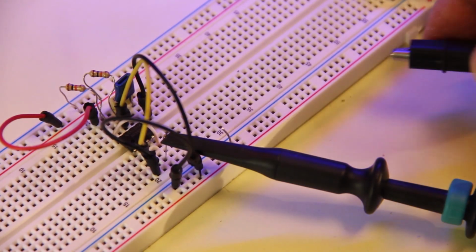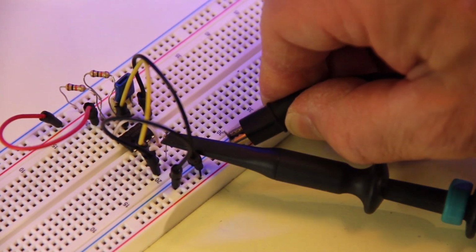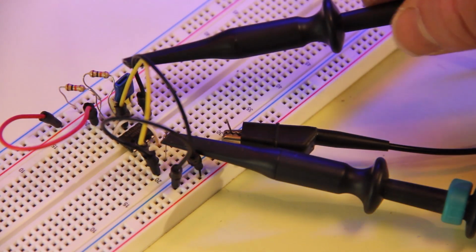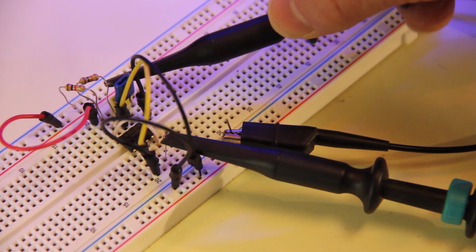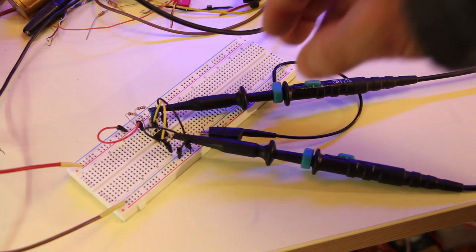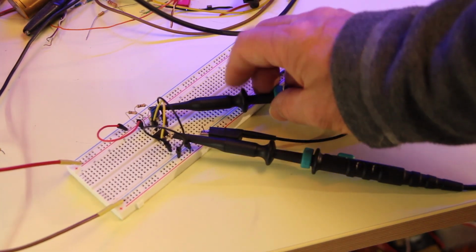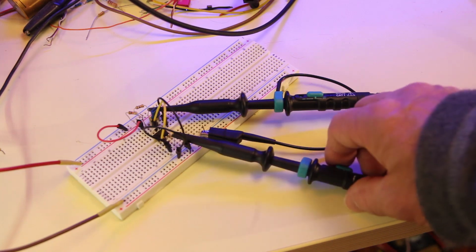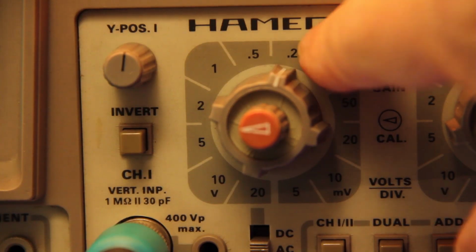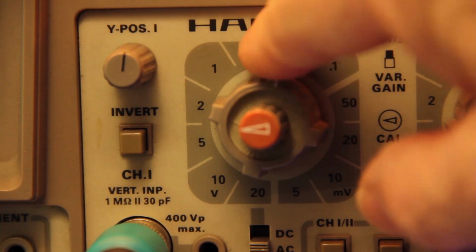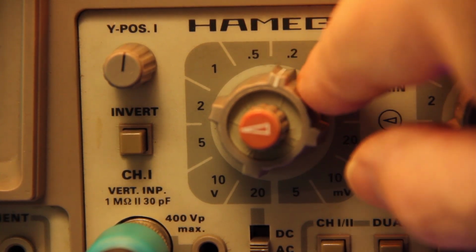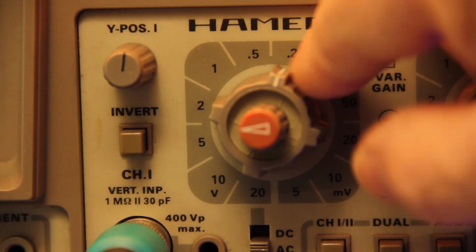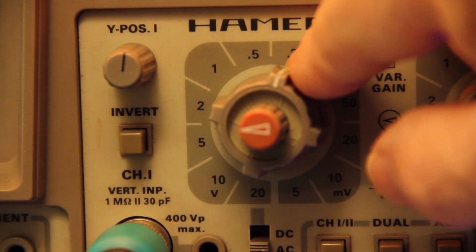You may wonder why use attenuated probes. There are two reasons. One is to limit the voltage if it is beyond the capabilities of the instrument. And the second reason is to minimize alterations to the circuit under test, since an attenuated probe has a higher impedance. Keep in mind that the attenuator scale should be scaled with the added attenuation of the probe. So, for example, with a 10:1 probe, this setting becomes 2 volts per division.